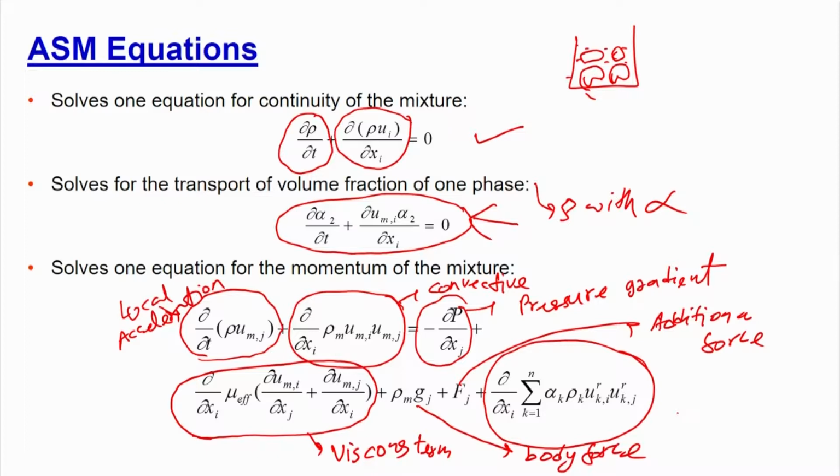Now, this is the term which has been extra included, so that we can get the individual information of both the phases, and that is very close to whatever the convective term is there. If you see these two terms, they are very close. They are the convective term. The only difference is that you are now multiplying it with the alpha i.